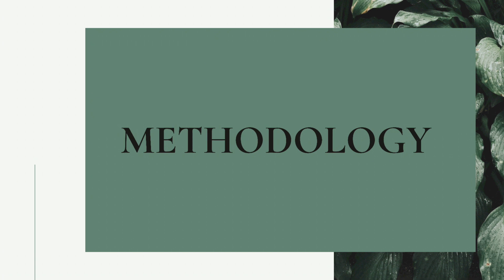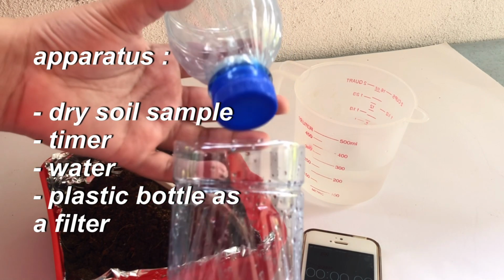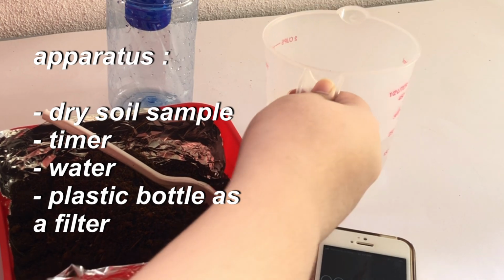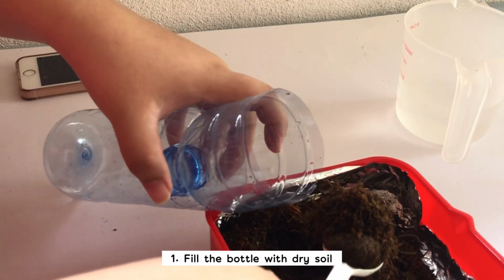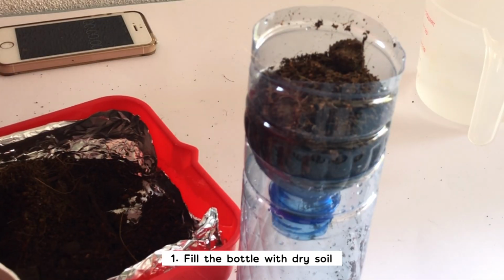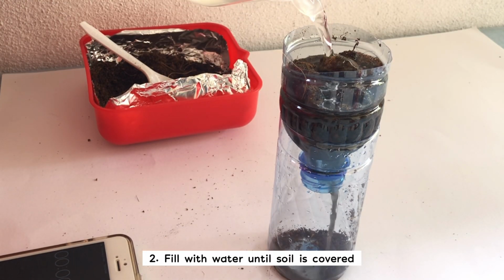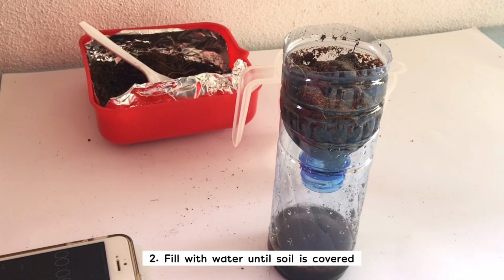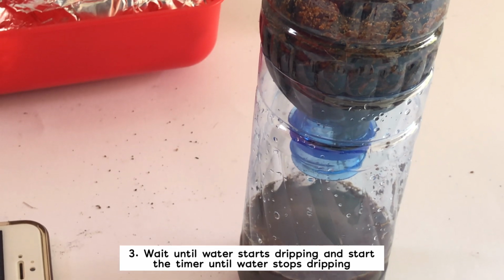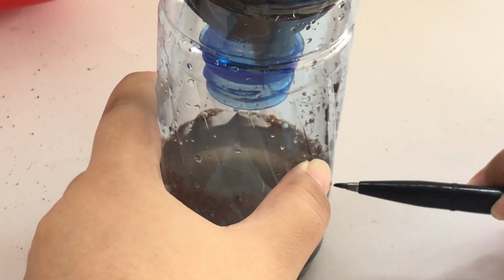For permeability testing, the apparatus needed are dry soil sample, a plastic bottle as a filter, water, and a timer. So for the first step, we need to fill the bottle with dry soil, and then fill with water until the soil is covered. And then wait until water starts dripping and start the timer, and then mark the height of the water.